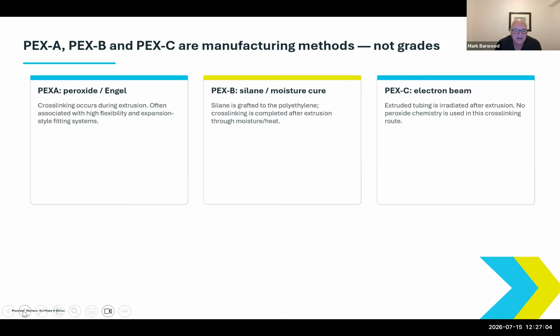a spec sheet. I'll tell you a quick little story. I was on a job site a couple of months ago, and I saw a contractor using a pipe called PERT, which is a polyethylene pipe manufactured in Canada. From everything I hear, it's good pipe. It's not actually PEX, it's PERT, something a little different. I said to him, "Hey, how are you allowed to use this in a high rise?" And he said, "Well, it's got S101, S102 approval." And I was pretty sure that I'd been told they didn't have that approval. So I went on their website, and sure enough, right on their spec sheet, they said S101, S102 approved.